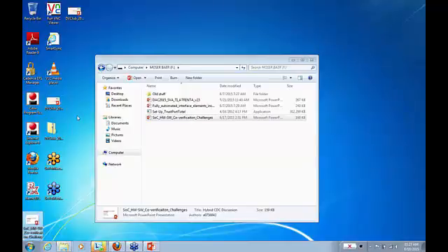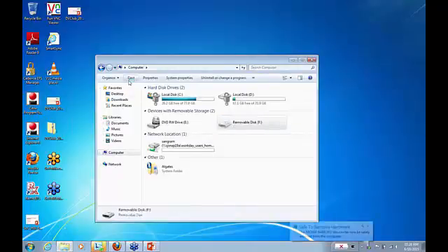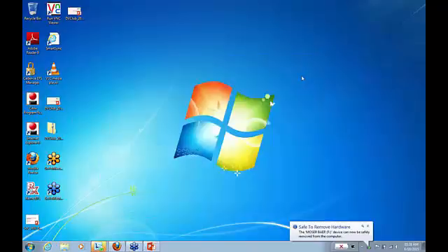Then your randomization plan comes into the picture. You can use some kind of C-based or file-based approach where you go altogether different. You use a Perl flow for all your testing, because you can use inline Perl to generate all your randomization functions, and then feed them as a definition to the VIP. On the randomization side, let us also understand that the unification architecture of all these different verification language IPs has to be planned from our side.